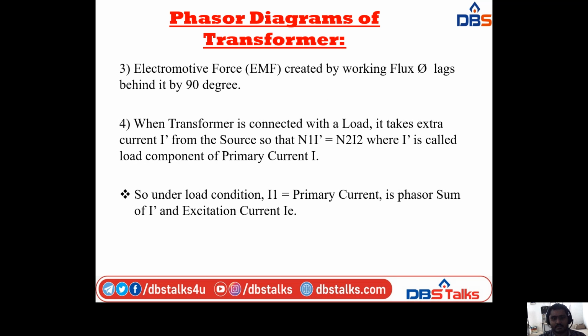Next, coming to the electromotive force created by the working flux. The working flux phi creates the electromotive force, that is EMF, which lags behind it by 90 degrees. The EMF created by working flux phi lags behind it by 90 degrees.